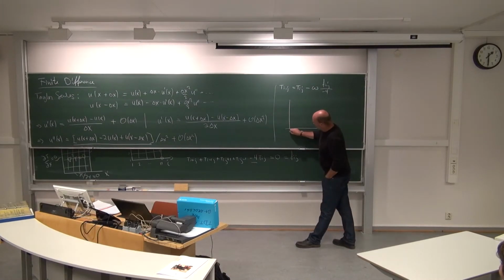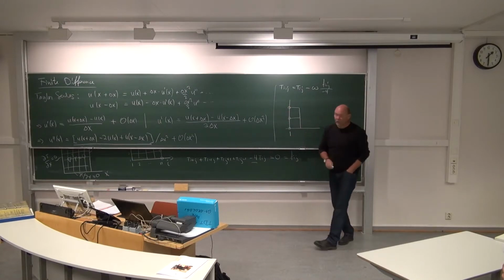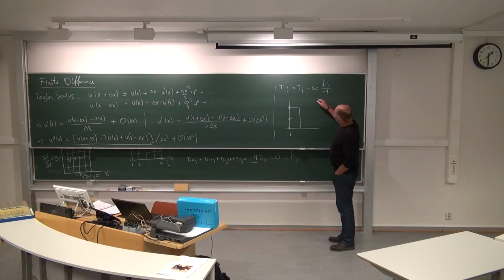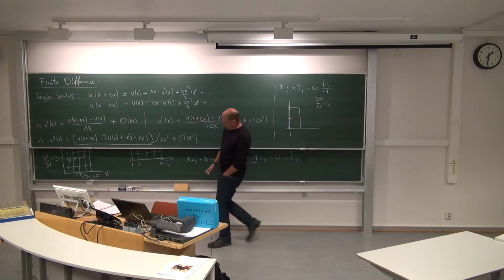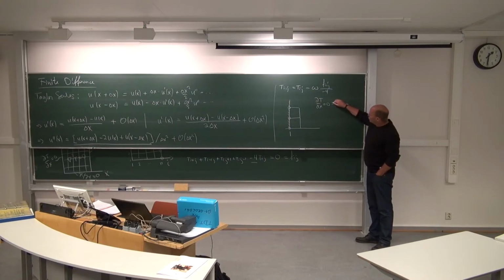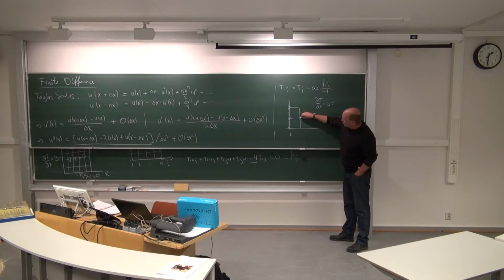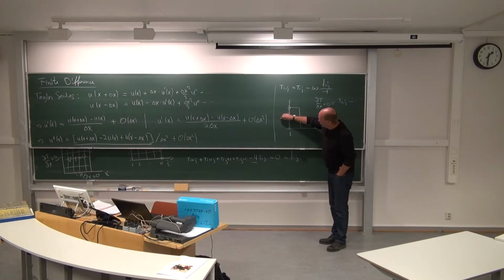Here is number 1. And here I have some cells. And these are unknowns lying on the boundary. That's number 1. What I want is to have this derivative equal to 0 at this location. This was on the boundary, index number 1 here. The x position 0 if you like, but the index number 1. I want this one to be 0. Okay, then we use this stencil. I create a derivative using the values to the right. That is T at x number 2 for all j, minus, and then I have something in here inside the wall.